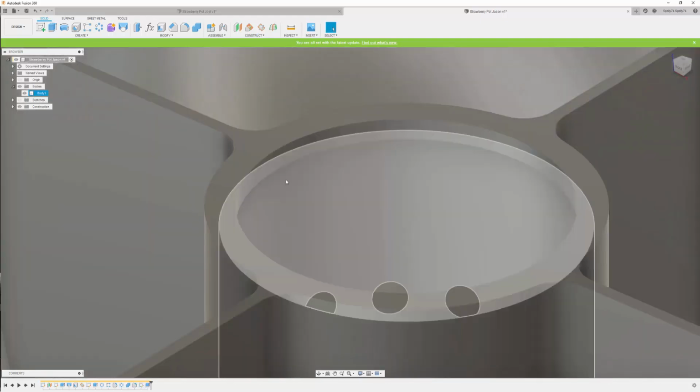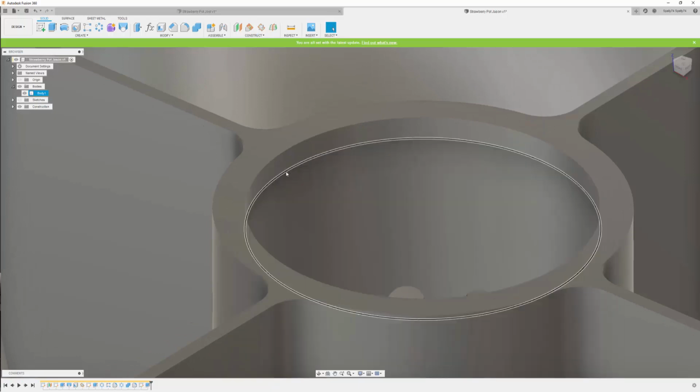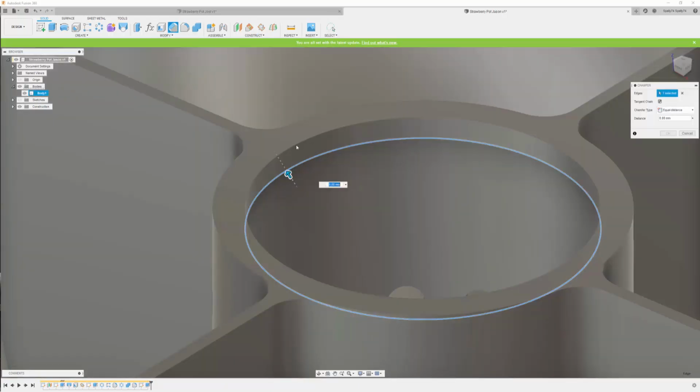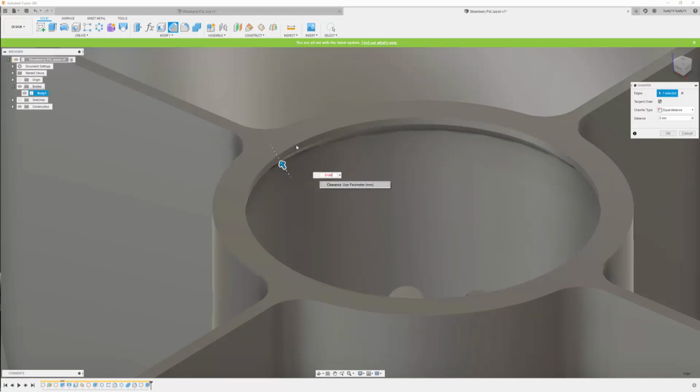So it's created me a lip. So obviously we can't 3D print this edge with the overhang without support, so we're just going to create a chamfer on that. So it's going to be 2mm plus our clearance. So if we change that clearance value to make the fitting of it just a little bit easier, I don't actually have to think about changing this chamfer. We know that it is still going to be valid.